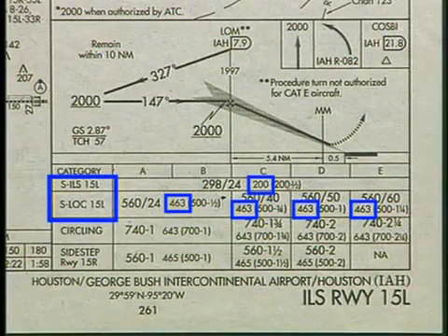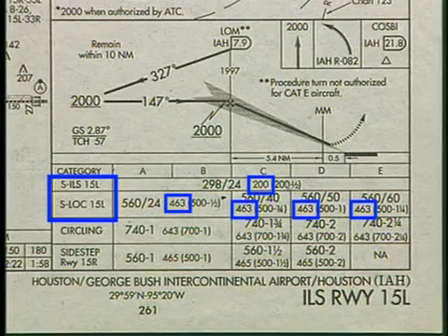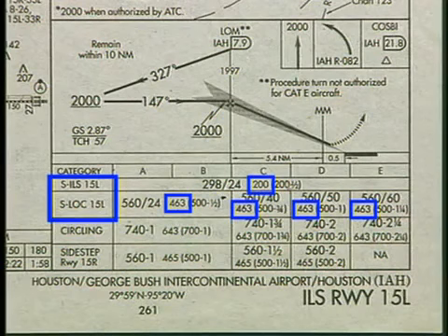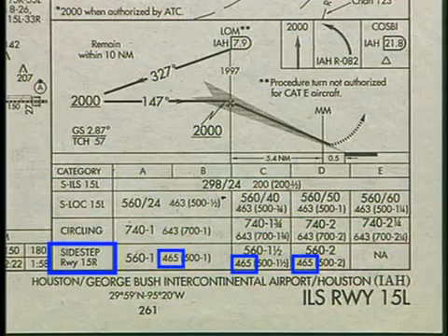The figure next to the MSL altitude and visibility is the height above a certain airport reference. For a straight-in landing, it is the height above touchdown, or HAT. For sidestep approaches, the HAT is based on the sidestep runway, which in this case is runway 15 right.